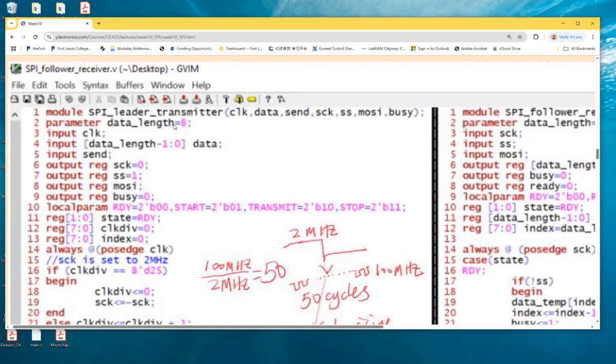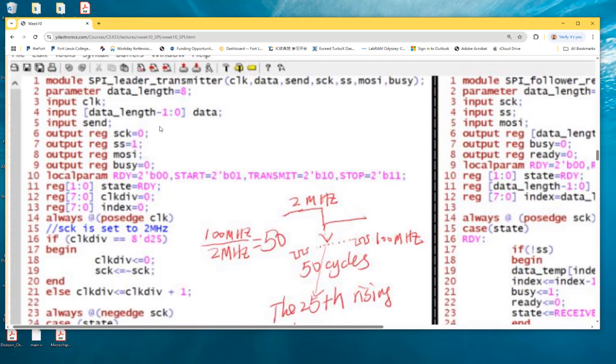It could be any length. And also, this allows for higher speed. So in that case, larger technologies is probably not a good fit for this communication, because larger nodes, larger transistors cannot run fast enough. So usually this is running at 1 megahertz, 1 megabits per second, but it can run even faster. You can see we can easily run it at 2 megabits per second in the example.